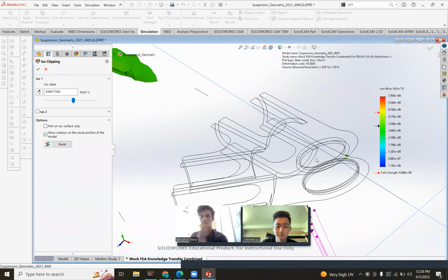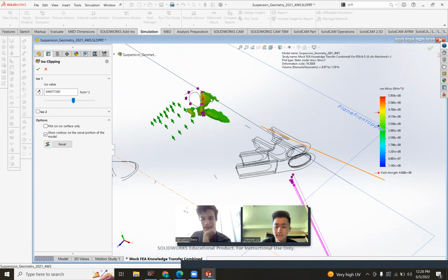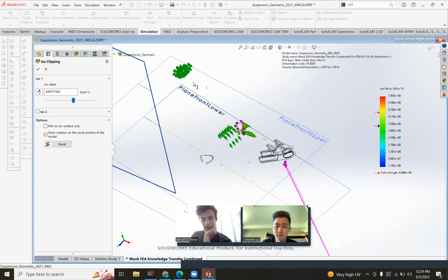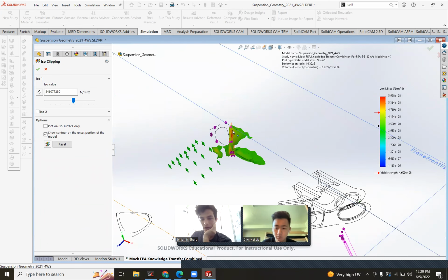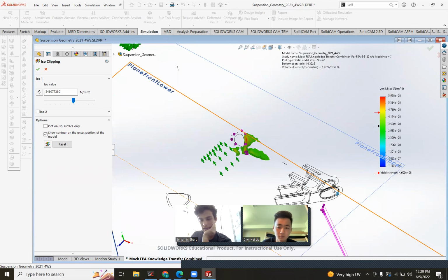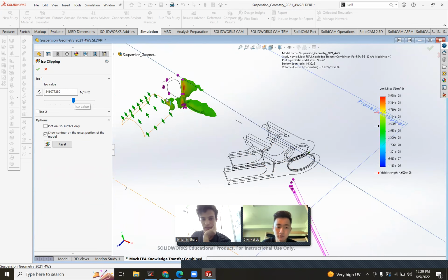So what I would do for FEA if you're doing it in SolidWorks is basically take all the steps that I have, try to figure out a better way of constraining the back, try to figure out a better way of making this a weld, and base your factor of safety on the failure that does not occur on tiny edges that SolidWorks can't simulate.